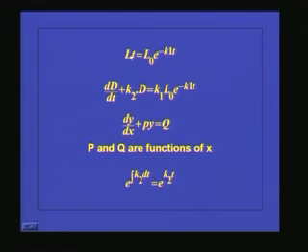So we know that Lt at any time, that means the leftover organic matter, is equal to L0 into e raised to minus K1 t, where K1 is the BOD exertion rate. And dD/dt we have seen earlier, dD/dt is nothing but K1 Lt minus K2 D. So we can write this as dD/dt plus K2 D is equal to K1 L0 e raised to minus K1 t, because Lt we are substituting by L0 into e raised to minus K1 t.